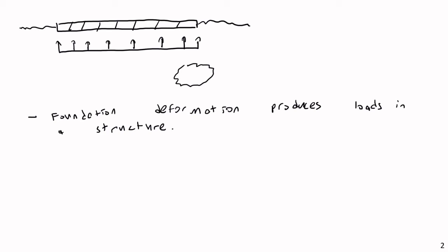So what your foundation engineer might come back and say is, yes, here are the loads, but considering both the loads and the variability in the soil, make sure your structure is able to withstand settlement of X amount of length. So that's so many centimeters, so many inches, whatever it might be. The way you make sure that's okay is that you then feed those deformations back into your structure.